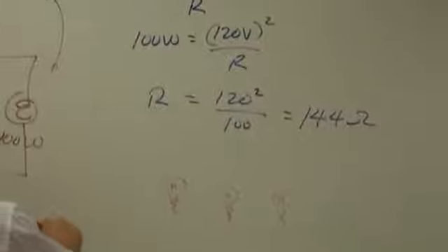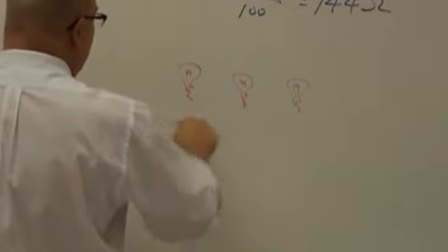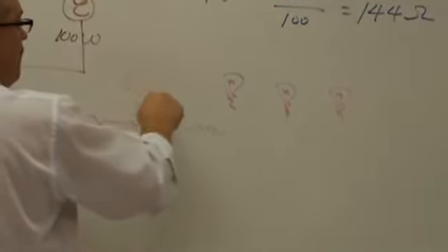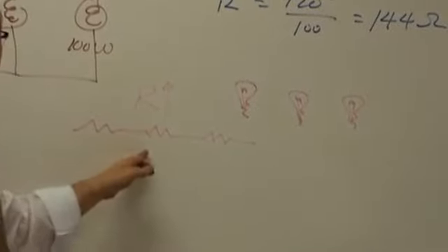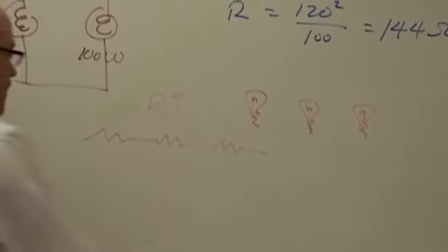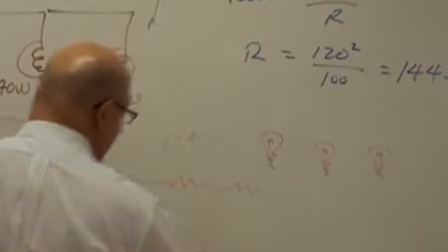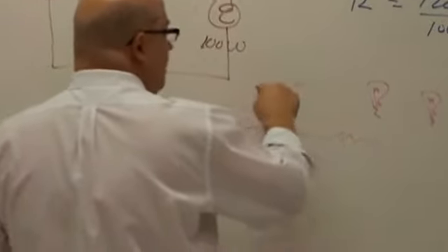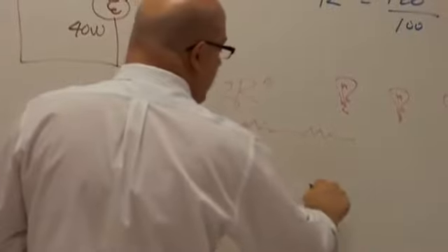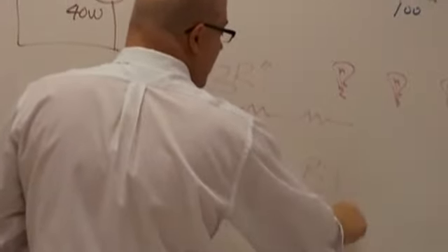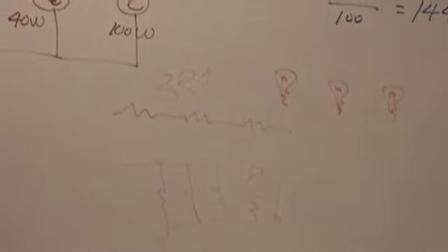When I hook up 3 resistors in series, what happens to the total resistance? It goes up. It's 3 times the original, right? But what happens when I hook up 3 resistors in parallel? It's less than each one. It's 1/3 of one of the resistors. So the resistance gets tripled in one case and cut to 1/3 in the other. It's a 9 times difference.